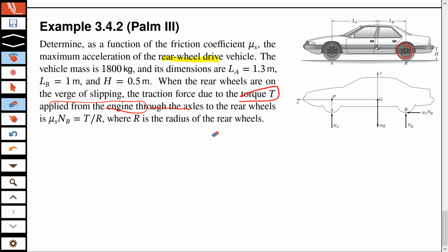लेकिन इस question में he wants you to use a notation which is different, so that B is for back, or maybe you can simply call this A and B. So you define NB in such a way that half of it is on one wheel and half of it is on the other wheel, and that will give you the simplicity that NB will denote the overall force on both the wheels. Okay, so अब अगर ये NB है और ये उसका friction है, maximum friction F max.